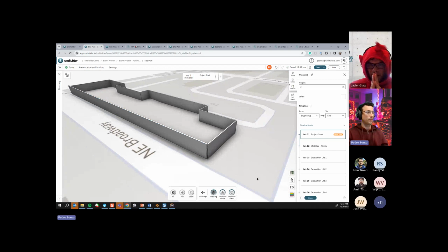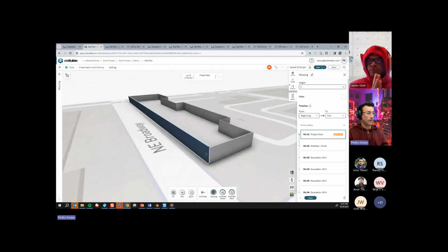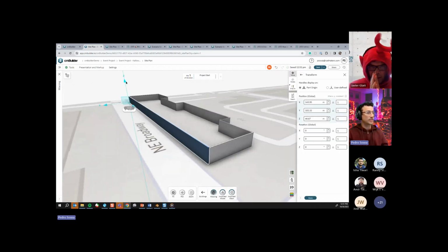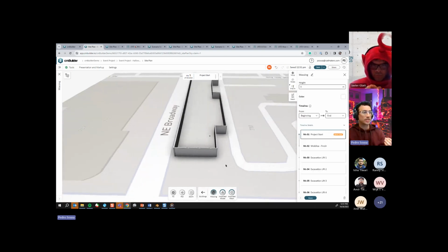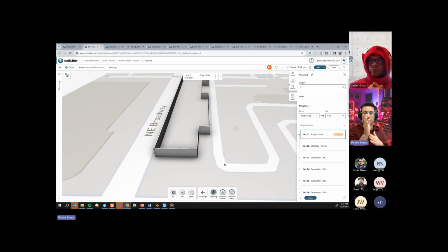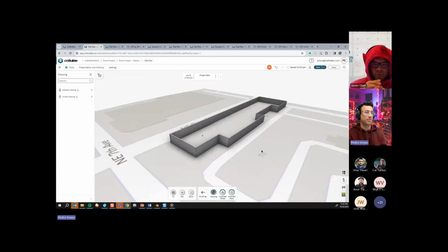There you go. Cool. Yeah, so this is a quick way for you to create that so you can work with your drawing to show the walls where they are. So you just draw one line, do an offset, close the ends, and then you have your wall already created over there that you can create a timeline for and adjust the way that you prefer.